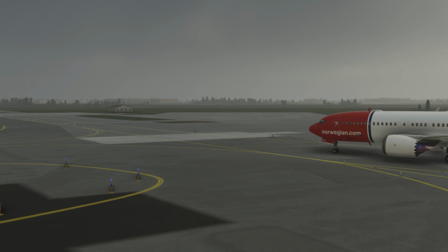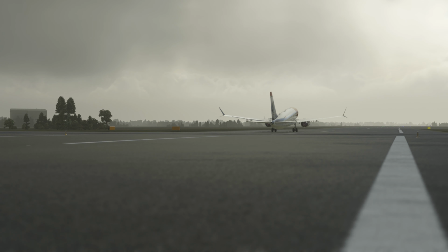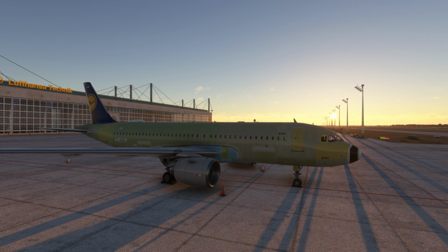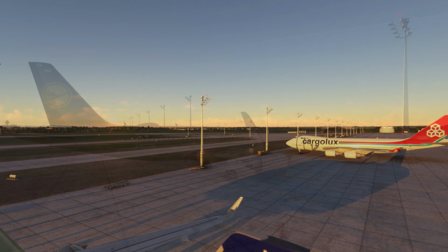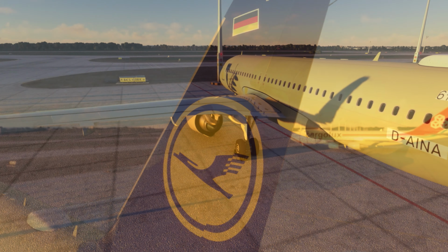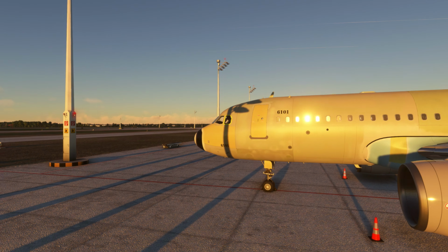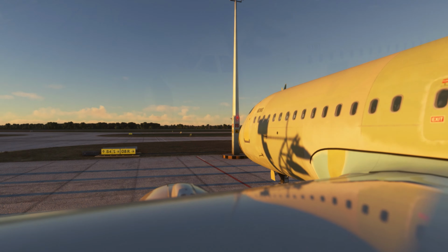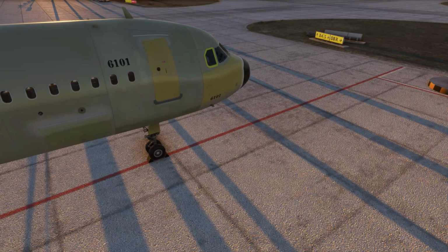Usually, the sequence of assembling an airplane is pretty much the same for all manufacturers. The first thing is the assembly of the fuselage segments. These are connected with frames and stringers. On one side is the relatively thin outer skin, and on the other side, special insulating mats can be placed in the space between formers and stringers.